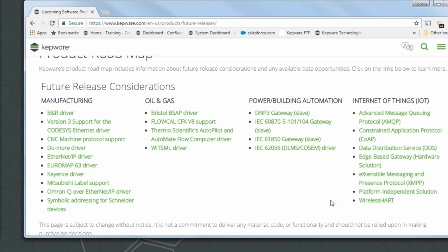So there's lots of self-diagnostics features in Kepware. There's system tags that you can read from any client. There's OPC diagnostics. There's channel and device diagnostics. And then there's third-party tools like Wireshark that you can use to debug things as well. So tons of stuff available. If you have those type of questions, again, you can contact our tech sales team.